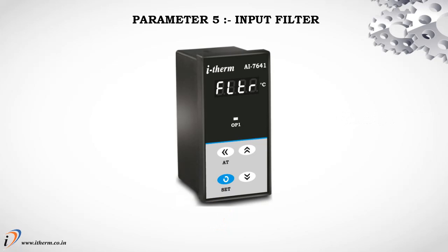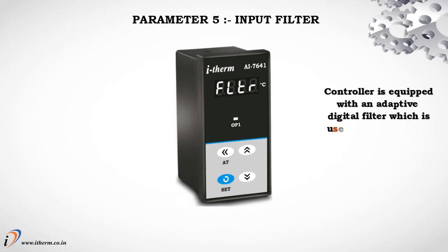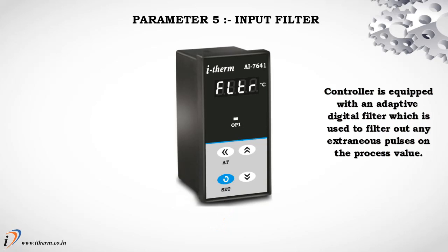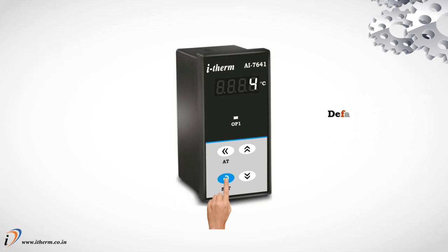Parameter 5, input filter. The controller is equipped with an adaptive digital filter which is used to filter out any extraneous pulses on the process value. Default input filter value is 4.